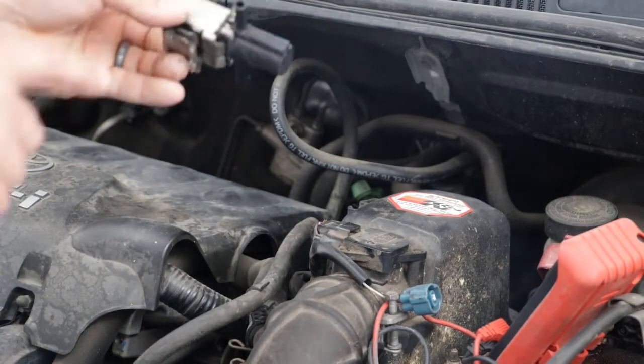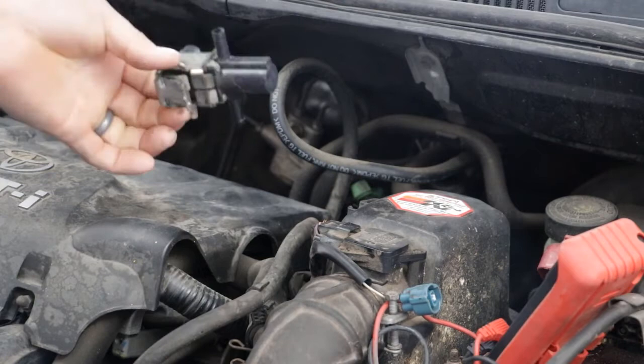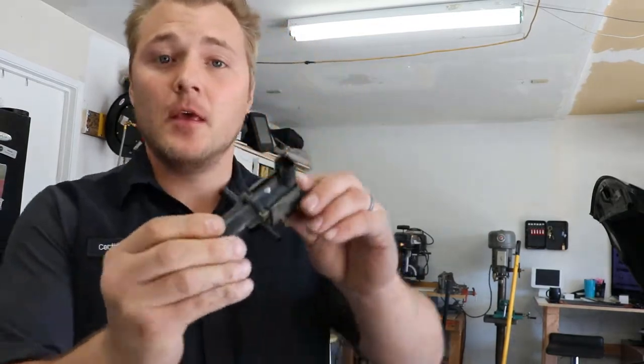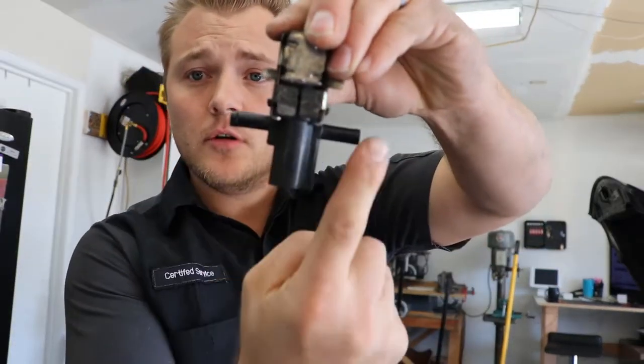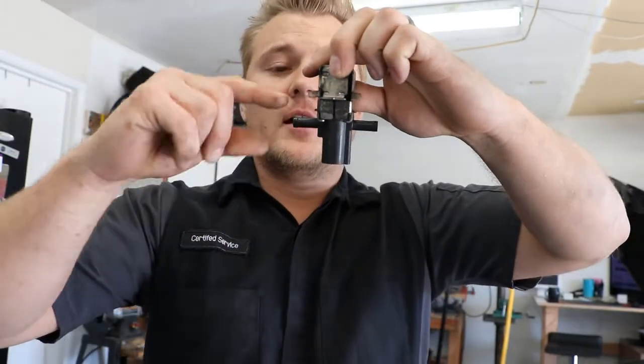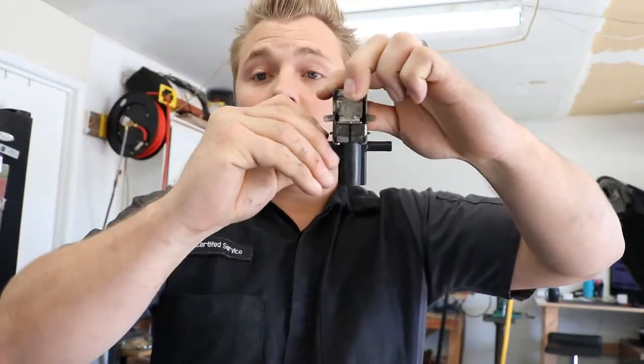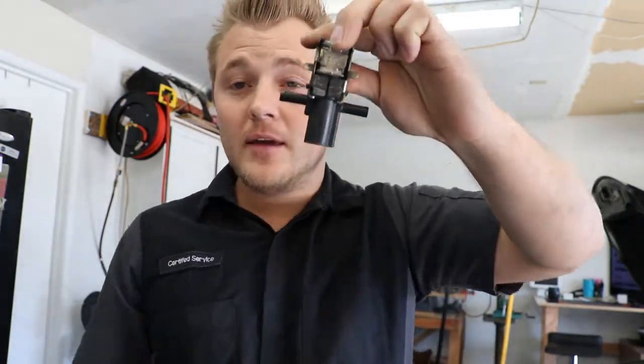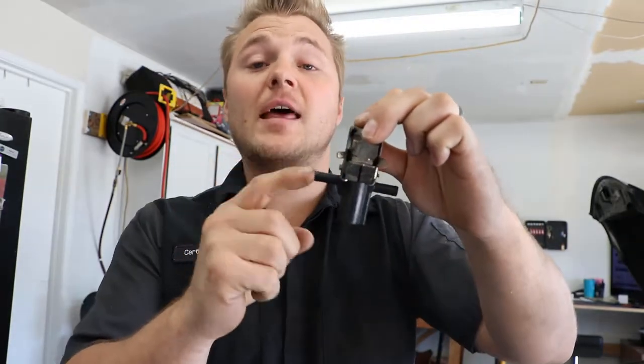Now, you shouldn't be able to suck or blow, air should not come through here, so I'm going to clean it up and give it a manual test. Alright guys, so now we have the purge valve out. I did clean it up a little bit. As you can see, there are two little nipples on this purge valve. The vacuum comes from the manifold and pulls suction through, and this will come back from the canister in the rear of the car. The system should emit a vacuum. There should be zero leaks, so this should not have any airflow through it if I blow or suck through it.